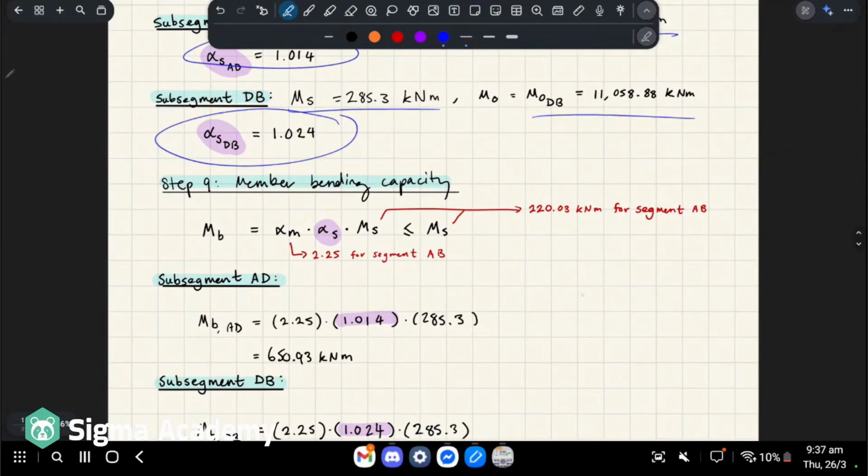So essentially, if you think about it, right, this is our beam arrangement. Okay, and it continues. The idea is that alpha M is calculated for each segment. So a segment is from a full restraint to a full or partial restraint, or whatever, from like full/partial restraints to another one. That's a segment, right?